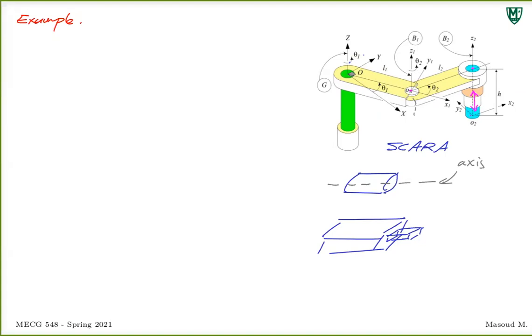So when we talk about moments, that's where the right-hand rule comes into play, when you have cross products. Basically, it's just a cross product, right? Right-hand rule. But in our case, your thumb shows the axis of rotation, and your forefingers show the positive direction of rotation. So if you rotate in the theta 1 direction, you're rotating positive. Let's say you're rotating 20 degrees positive.